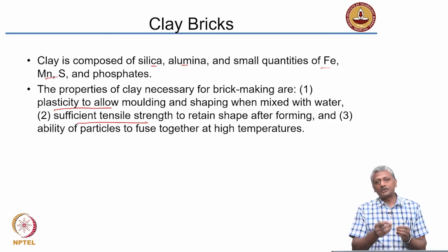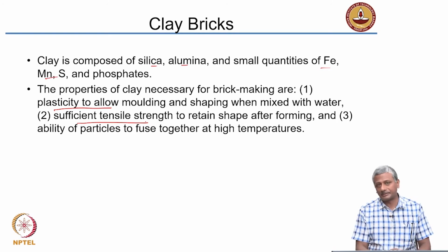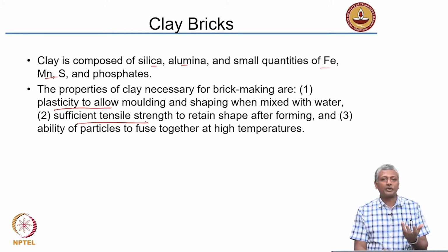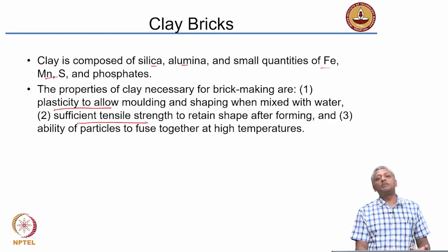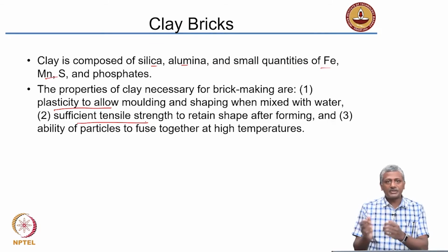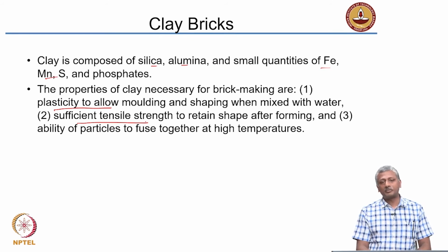If this water dries out too fast, it may lead to desiccation or drying, cracking of the clay. Now, you do not want that to happen obviously, even before you form the brick. So, the tensile strength should be capable of resisting any cracking tendencies of the brick. Okay. And finally, after the brick shape has been formed and you have dried the brick, you then need to subject it to a very high temperature firing operation.